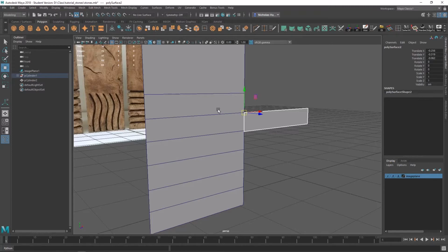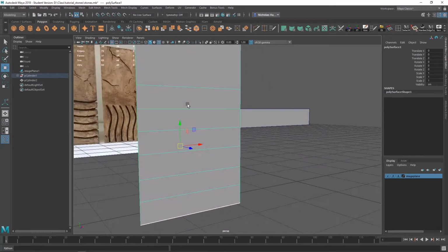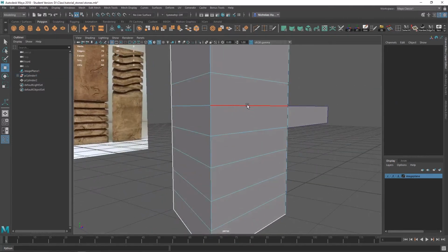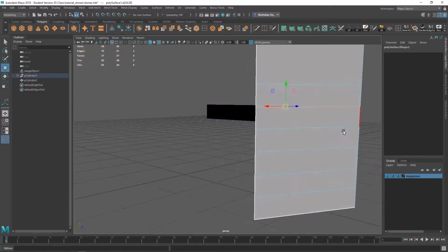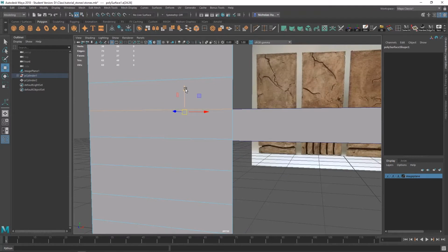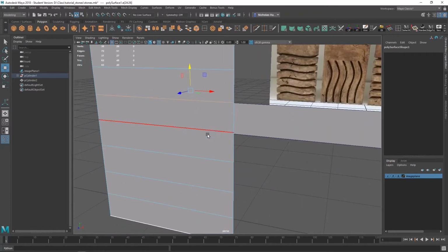And now with object mode, we should be in object mode. Just click your big box here. Then go to edge mode. Double click your edge line. It should select all the edges all the way around. And then click this right here, this up and down handle. And then holding down V again. Actually, wait, go to this one right here. Just double click that edge.